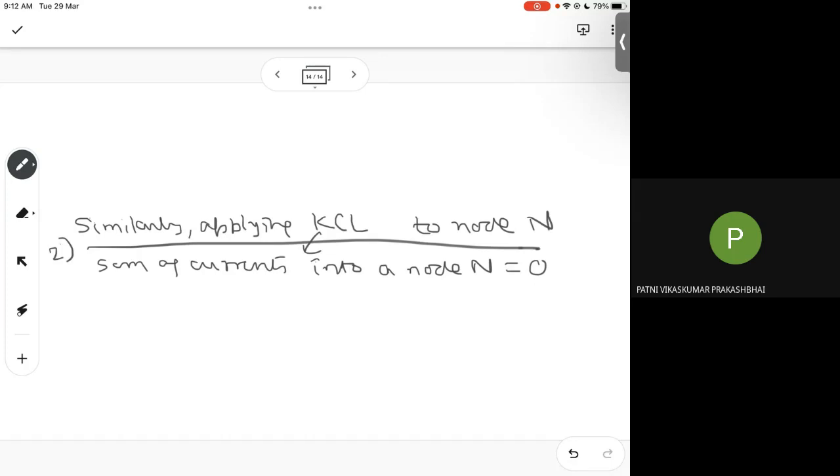Now here, what is that? Sum of currents. So my equation, just like we have done in KVL, becomes I(Z,T), which is a current, minus G delta Z, which is the conductance, that means 1 by R, multiplied by V(Z plus delta Z, T). Again, it becomes a current equation. G is, though not 1 by R here, a conductance, so it has the same units, minus C delta Z.